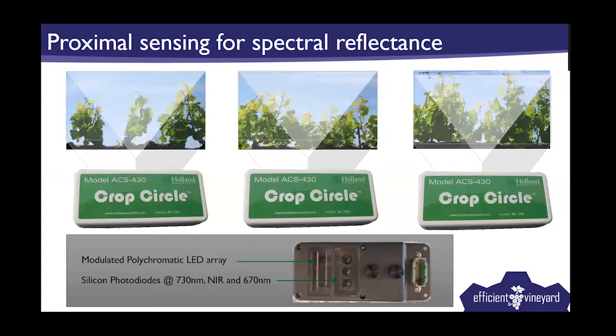And this sensor spits that out into a data collector that's tied in with GPS. So you're able to get the actual reflectance at 3 different wavelengths. Because of that, you can calculate a whole bunch of vegetative indices. So you're not limited to NDVI. If you want to use something else, you certainly can do that. But unlike a passive sensor, you're getting high resolution, really good information. And a passive sensor is just going to be a little more coarse than that, because as you saw on the previous slides, your waveband spectra, it's a range. It's not a value.